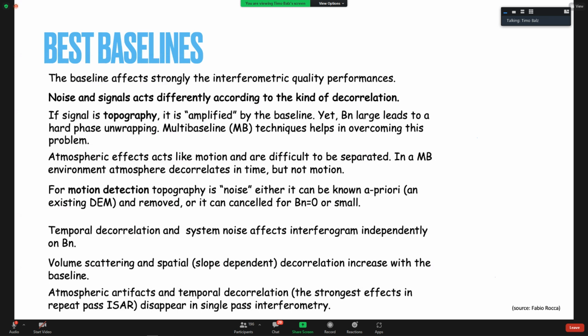But at what position exactly they pass again, there is a certain randomness to that. So you cannot really say, I want a 200 meter baseline for that. One could, from archive images, look up and say, this baseline is too long, I don't want that, but for newly acquired images, you can't precisely control that.